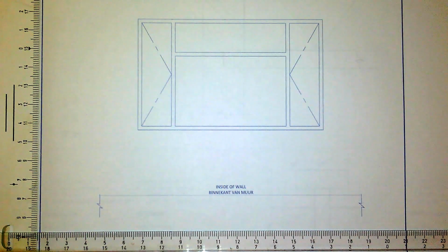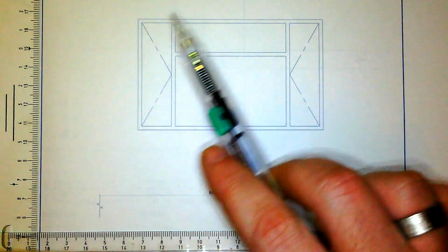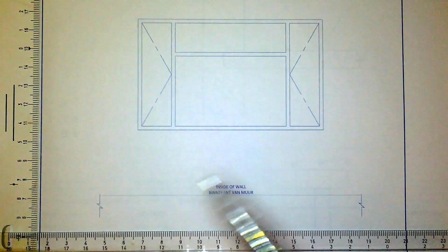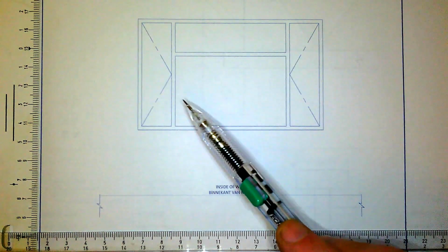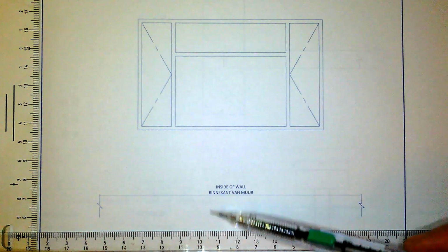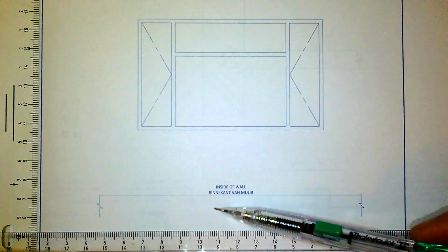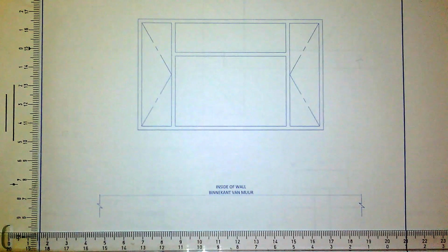Okay, so I'm going to show you how to do the top view of a window, effectively a section. So imagine a floor plan, we have to draw in a window. How is it actually done? Now what's nice about it is we always draw the top view of the window symbolically. So it doesn't actually matter what design window we have, it doesn't matter if it's metal or wood, it doesn't matter how many panels it has, all that matters here is the length of it, and then the thickness of the wall. So obviously this wall here is normally 220, but it's drawn to scale. We don't even need the scale for this exercise.